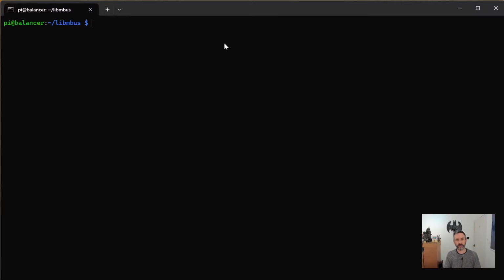And he says that the primary address is usually 0 or 1, so there's all sorts of conflicts, whereas the secondary addresses are unique. So the first thing we do is to scan the USB connections for an MBus terminal, and the command to do that looks like this. It's called MBus serial scan secondary. We give it a baud rate of 2400, which is kind of a recommended default, and then we tell it to scan the USB connections.